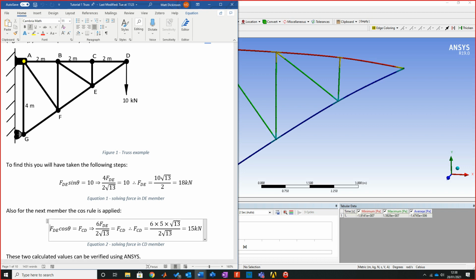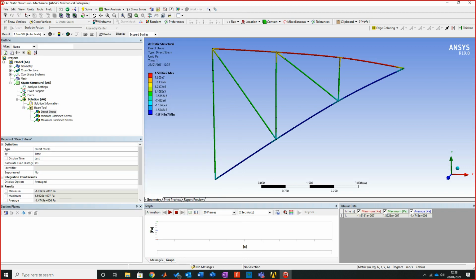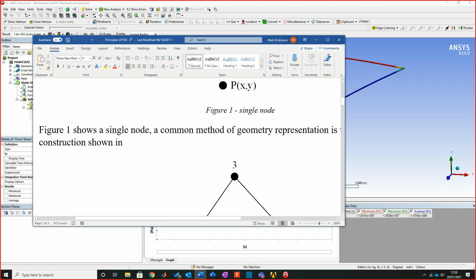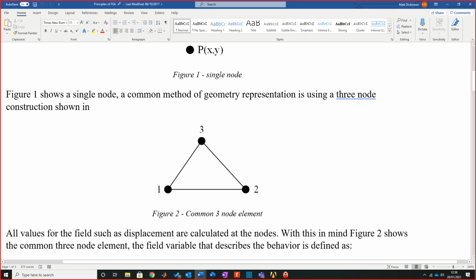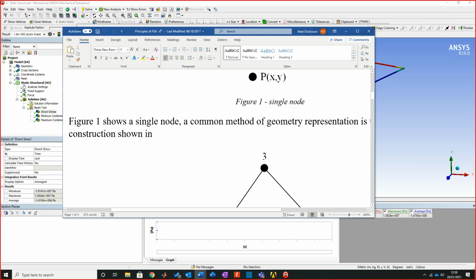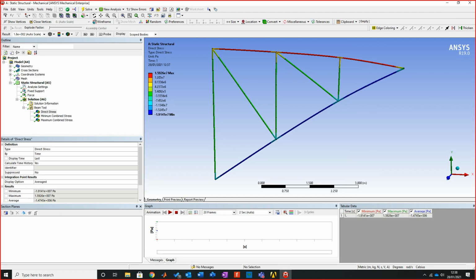Now, this is where ANSYS really shines, and I do quite like this. Remember, right at the start of all this, I started to discuss with you the idea of error. This is simply the error of the relationship of these nodes, how they're talking to each other. Simply that, all the way through. ANSYS literally say, if you have a calculated value between 1.2 and 1.5, you're in the right ballpark. Because their error is recorded between 1.2 to 1.5. So in other words, we are in that range.